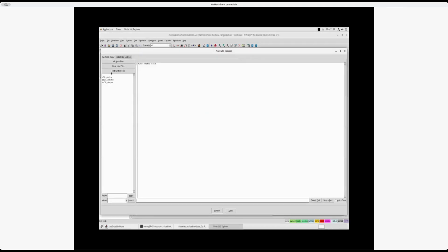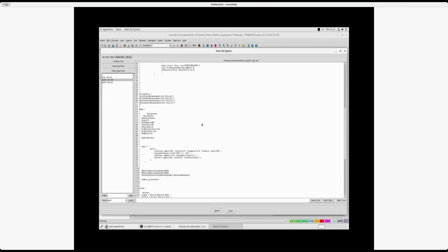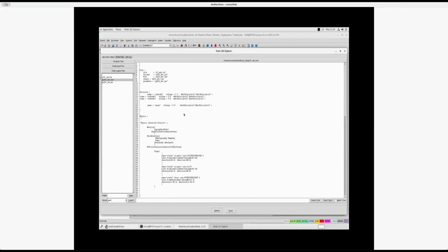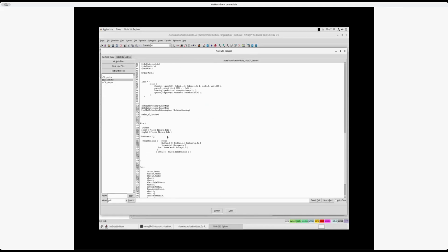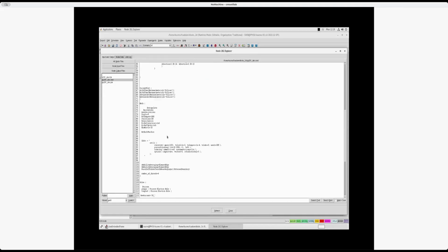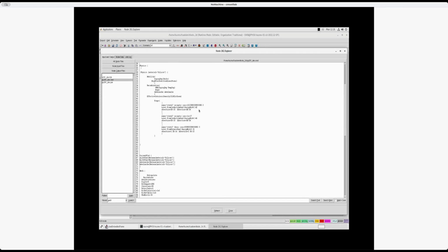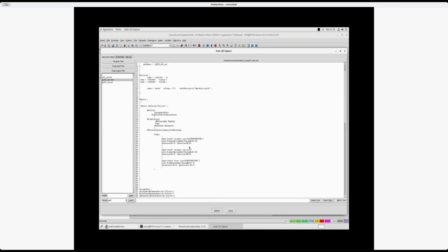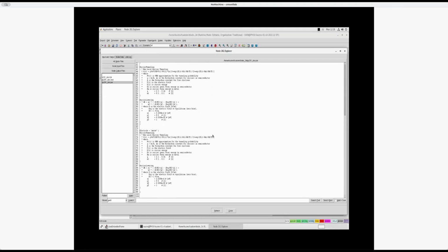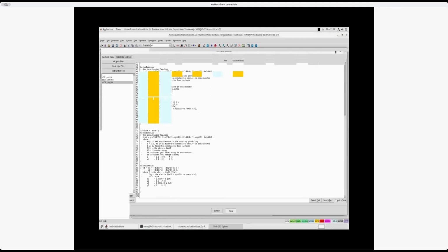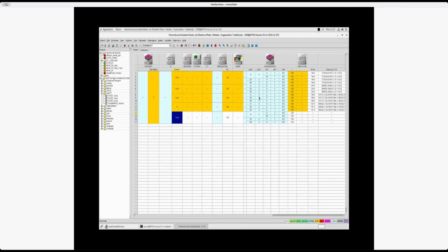Now I can double click here and I can see the script that has been generated with all the parameters in, with the irradiation. If you look at the irradiation model here, this is the definition of the traps for the irradiation model, which is calculated from the fluence. There's some math being done, so you cannot see the value directly, but it's there to be run, some parameter file. So this is ready to run. So this is pre-processing. It's a bit of a tricky concept, but once you get it, it's very useful.